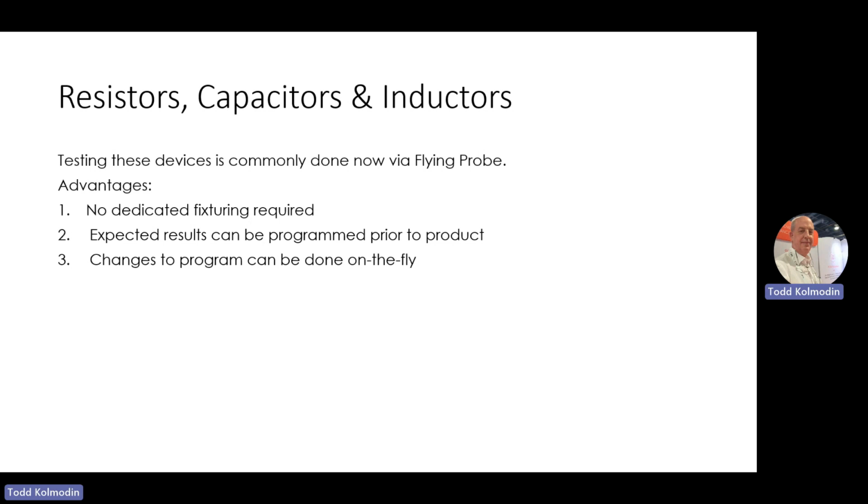So they went into another material type scenario where they use a resistive laminate, where there's copper on the outer surface and a resistive laminate under that. And so to create the necessary resistance, you etch off a certain area of the copper, exposing the resistive material, and based on the square, you will develop that resistance. It's very predictable. And if etching and everything is working as designed, you will get a very strong resistor out of that. When testing these things, a lot of it now is in the material type resistor.